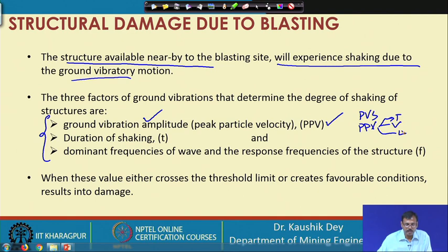So, first, the amplitude is very important, that is, the peak velocity is important. Then the next one is the duration of vibration for which it experiences shaking. So, that is very important. The third one is the dominant frequency of the wave and the response frequency of the structure, that is also important.